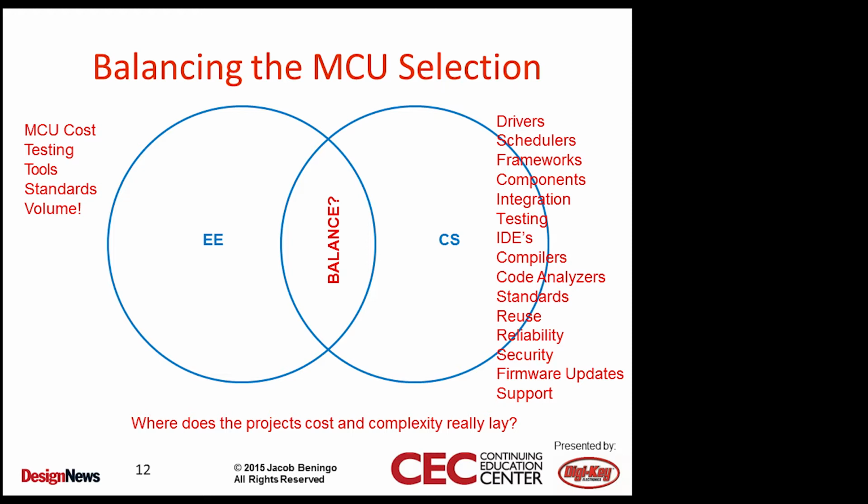So maybe that's one of the things as I'm working with the electrical engineer and he's finding that microcontroller that's perfect for his electrical needs, we're also going and saying, hey, you know what? This one doesn't perfectly meet our software needs. How about this other one? And then you work back and forth until you find that middle ground where you have a good microcontroller that fits the electrical characteristics and also provides a good ecosystem around it, with a lot of the tools needed by the software developers to get their job done properly. So these are some of the things we should be thinking about as we try to balance these two different viewpoints.